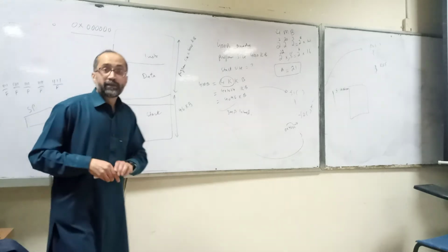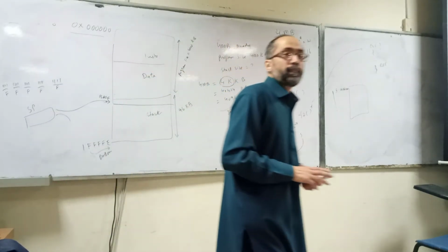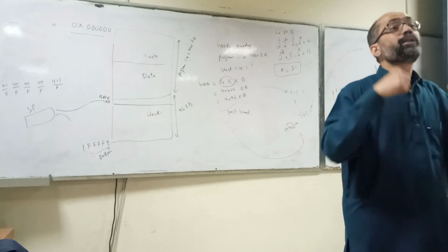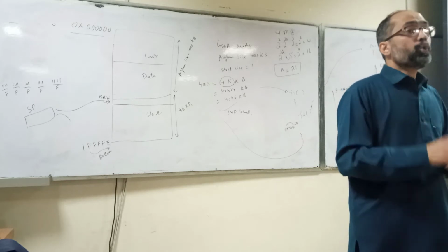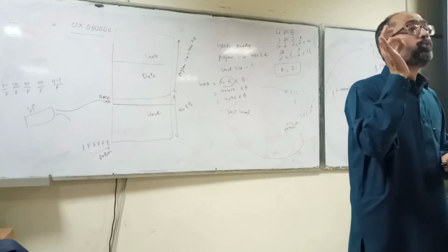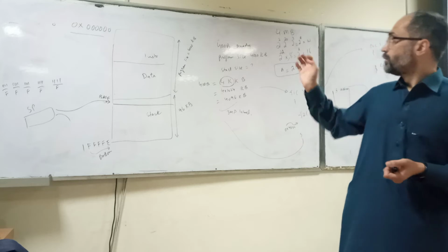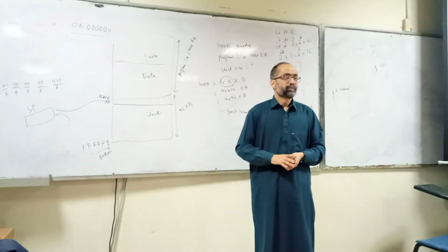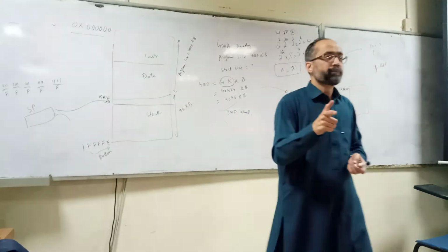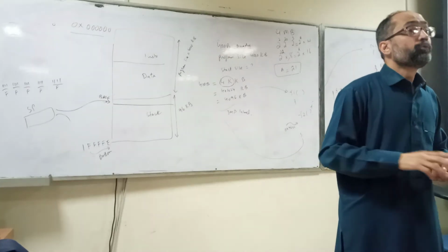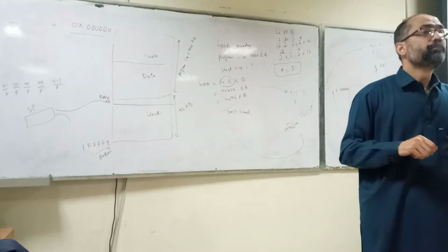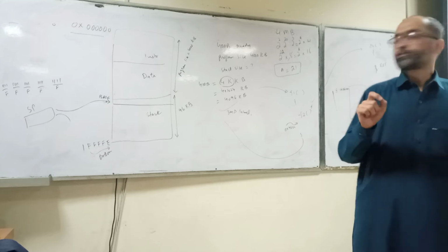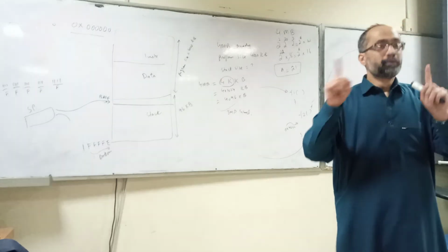Now we studied different addressing modes. We studied register indirect with pre-decrement. We studied register indirect with post-increment. Which addressing mode will be used for maintaining the stack? Because the stack is moving from bottom to top, we are moving from bottom to top. Pre-decrement. So to maintain a stack, we will use register indirect with pre-decrement.